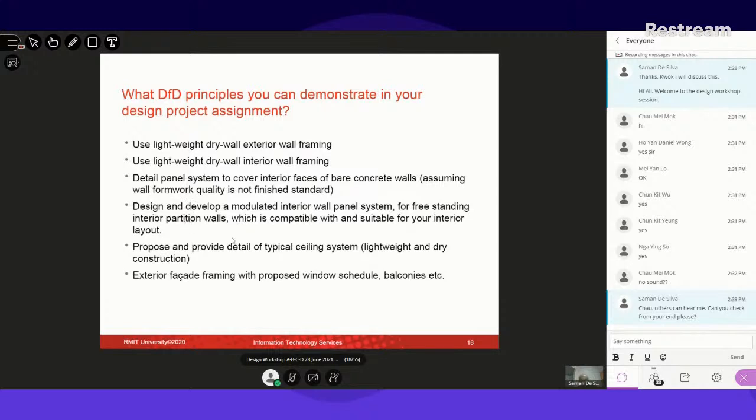So nowadays, most of the time, we try our level best to incorporate all the internal walls in dry, lightweight construction. There is another advantage of these things. Speed of construction has increased enormously, the acoustic quality you can improve, and fire resistivity you can improve quite effectively. So there are a lot of advantages.